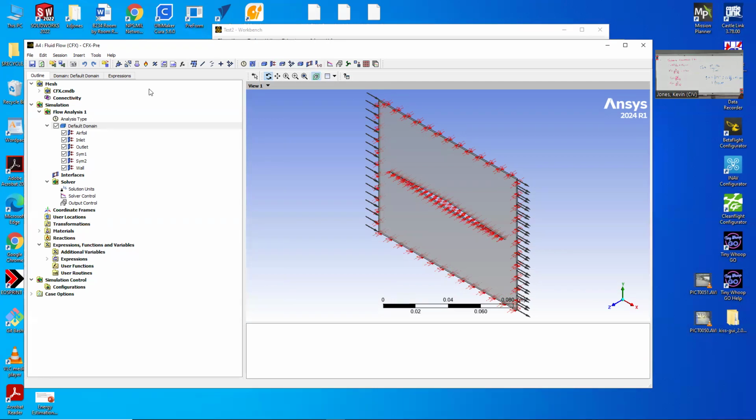So you could run it turbulent, but then there's a couple of problems. If you have turbulent flow, then you really want an inflation layer. But I think the inflation layer is incompatible with the mesh refinement, so you couldn't use the mesh refinement. I think that's a true statement.